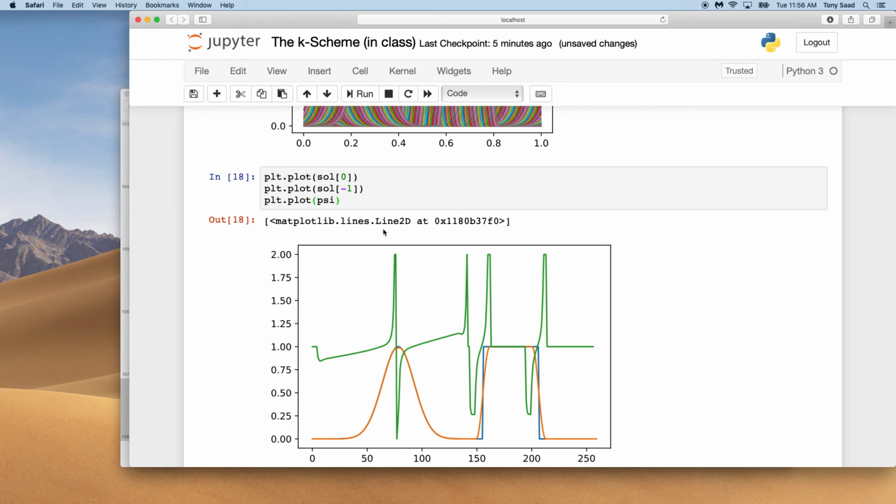In smooth regions, psi is somewhere in the second order TVD region, okay? So it's where these peaks are that you're switching to an essentially first order scheme, whether downwind or upwind. But this guarantees you monotonicity, okay?